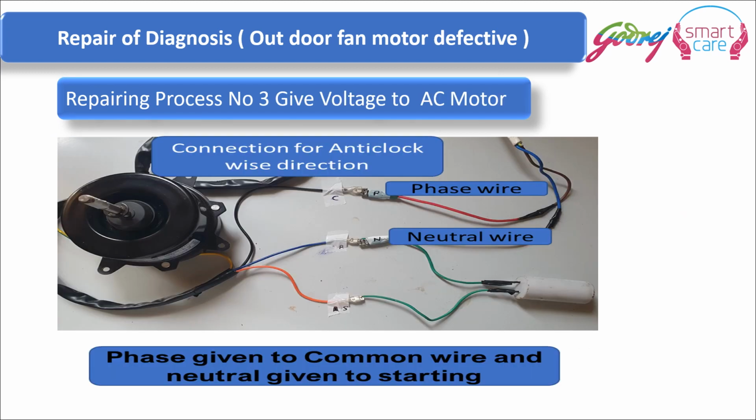We have to supply voltage to the AC motor, with the phase given to the common wire and the neutral given to the start wire.